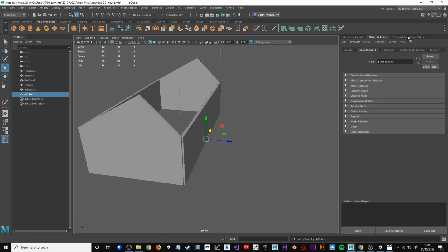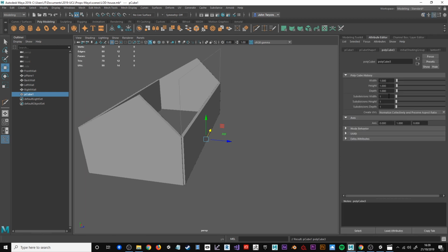Now in this case, again, we know what the parameters are we're working with. We've got 1000, but I'm going to give it 1010 because we're working beyond the end of the building. That might need a little bit more, but we'll work with this for now. Height, thickness of a roof, I'm going to give 5 centimeters, and a depth of 200.